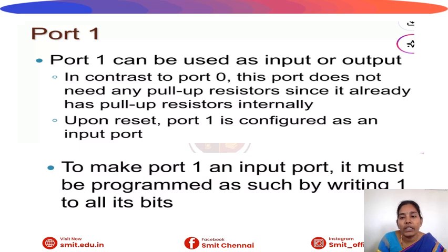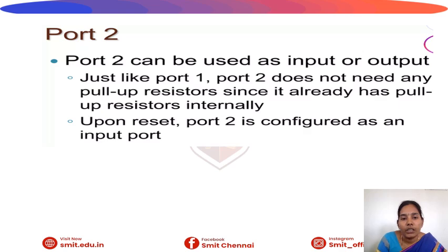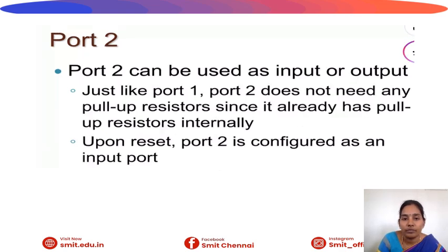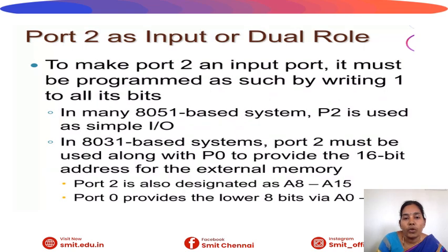Port 1 is used as an input port or output port. Port 2 does not need the pull-up resistor because it has internal pull-up resistors. Port 0 you can use in a dual role, for input-output as well as the address lines. Lower order address lines are used in port 0. In port 2, addresses 8 to 15 are used.